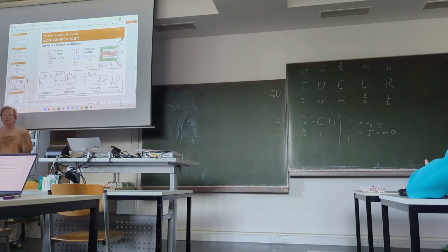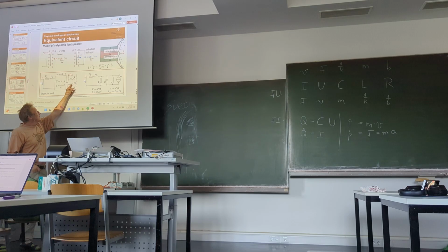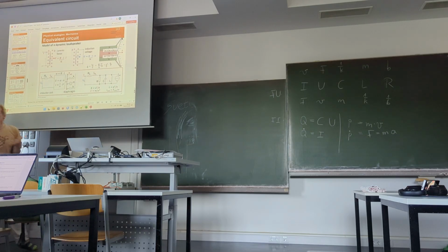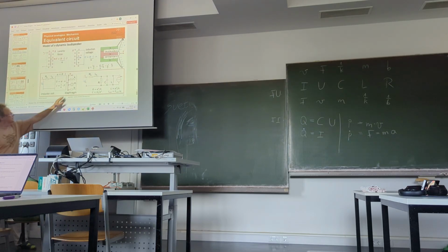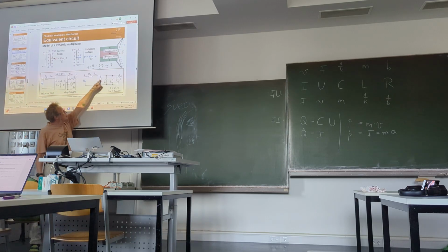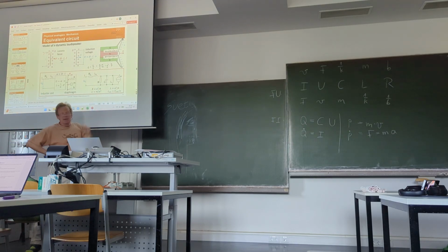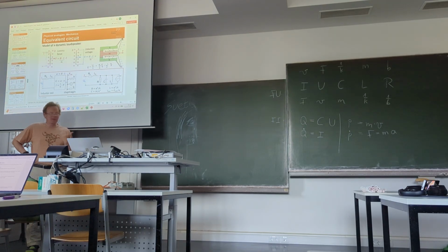But due to the coupling, there is more, because the diaphragm has a mass, it has elasticity and also damping. And all these mechanical effects also affect electrically measurable quantities. This looks more like a complicated circuit with some components here in parallel. Okay, those are our three main properties from the diaphragm.